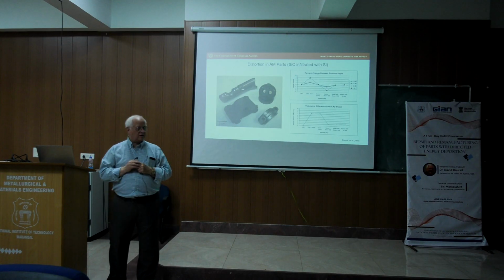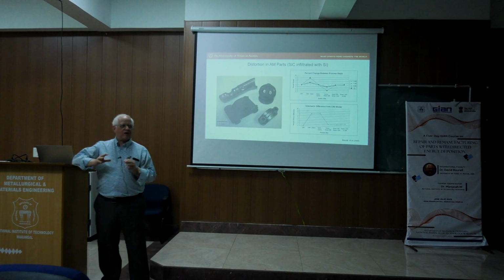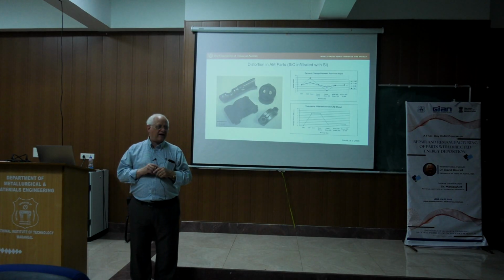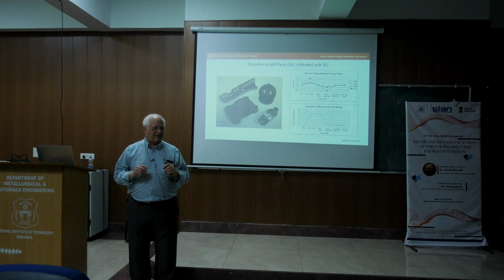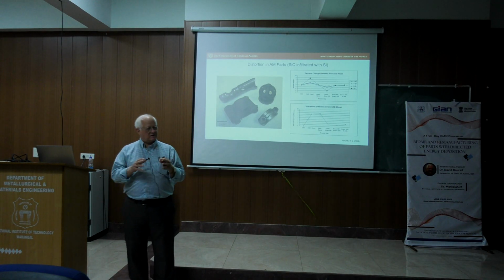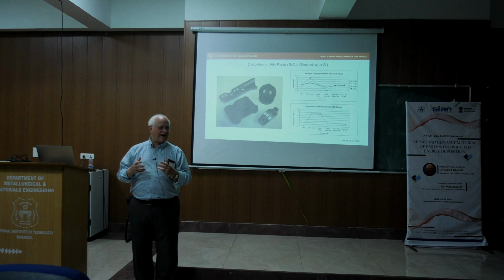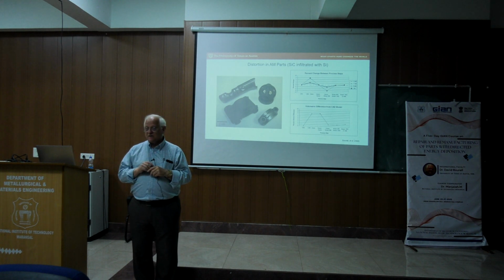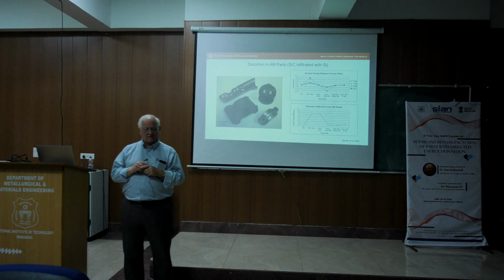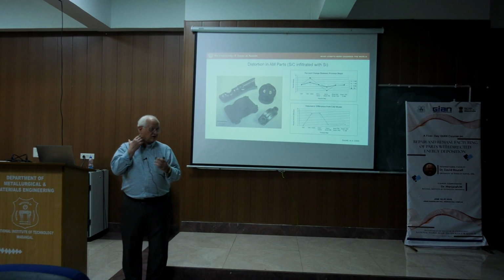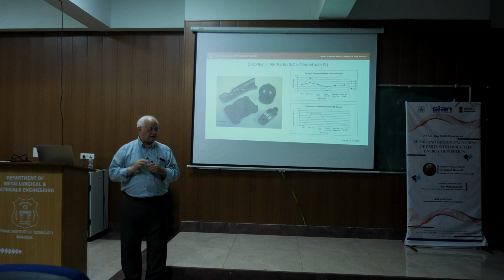One of the features of the binder we used is that it's what's called a high ash material. That is, we used phenolic. Phenolic is a high ash material. What that means is when it burns, it leaves behind about 50% carbon if you completely dissociate it. So what we did is we mixed the silicon carbide with the phenolic, put it in a laser sintering machine, and scanned it to create a part.